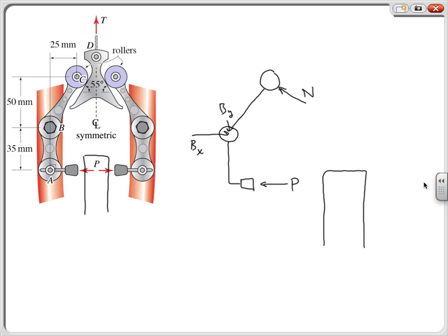And if this is coming forward, then a velocity vector for the wheel at the top here would be coming out of the plane of the figure at us. The nature of friction is always to oppose this motion, so the friction force on the wheel rim would go in the opposite direction. That is, it would be going into the plane. But we have an equal and opposite force on the brake pad, and so that would look like this.